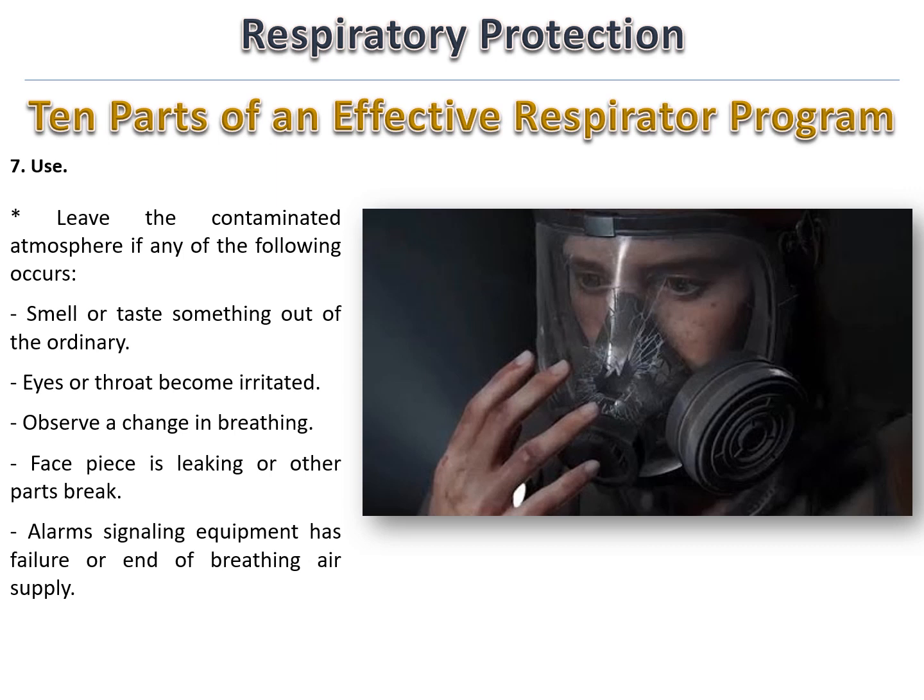7. Use. Leave the contaminated atmosphere if any of the following occurs. Smell or taste something out of the ordinary. Eyes or throat become irritated. Observe a change in breathing. Facepiece is leaking or other parts break. Alarm signaling equipment failure or end of breathing air supply.